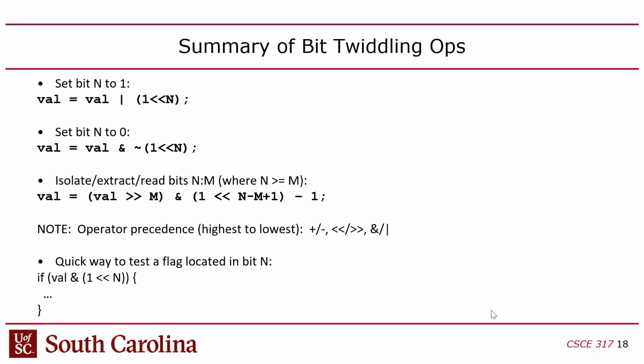The other thing too is you don't want to try trial and error, because keep in mind that if you're writing this code for an embedded system, this is not 145 and 146 where you can just run Eclipse and test it. You're writing this code, you're downloading it to an Arduino, and then you essentially get cut off from it. So Arduino has no debugger. If you do this and it doesn't work, there's just no way to know on the Arduino. You can try to print something to the console and do old style kindergarten print debugging, but there's no real debugger on Arduino. So you have to be a little bit more careful when you write embedded code, because you don't have the luxuries you do of writing code on a PC.